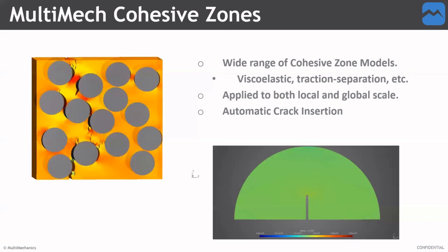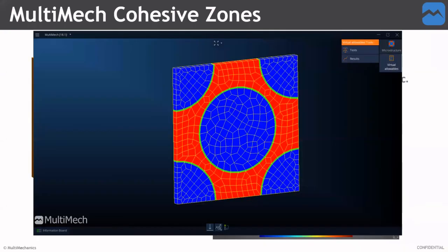Very good. The next question is, does MultiMech support ceramic and metal matrix composites? The answer is we support basically any kind of material. Because we are based on a finite element model, there is no assumption on the individual constituent material behavior. So we have quite a few constitutive models implemented, including orthotropic elastic, linear viscoelastic, nonlinear viscoelastic, and elastoplastic models, and the list keeps growing every year. And so for those types of materials mentioned, we already have the models necessary to account for them.